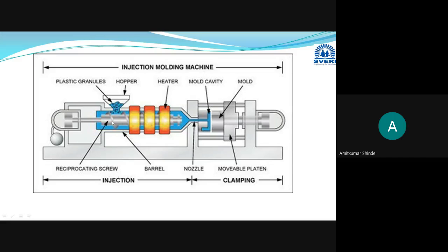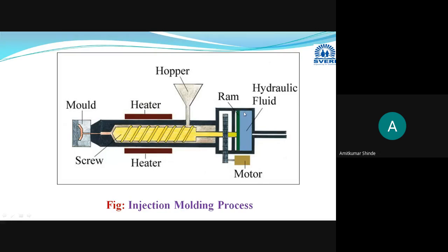Now, depending on the nature of the instrument or source you have used to apply the pressure, two types of injections will be there. Already I have explained that principle. If you have applied the force, or used the ram type, for injecting the melted plastic material into the mold cavity through the nozzle, then it will be ram type.